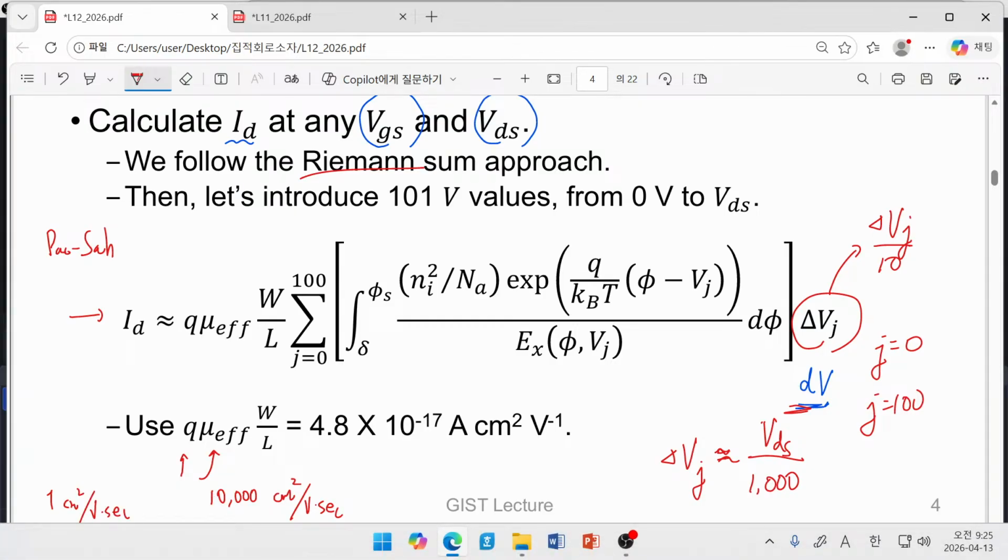That is really achievable, but way too low to be used for your transistor. My suggestion is that when you really use your transistor, your mobility will be around a few hundred or several tens of square centimeter per volt second. Please do not overrate it, or use too low a value for your mobility.